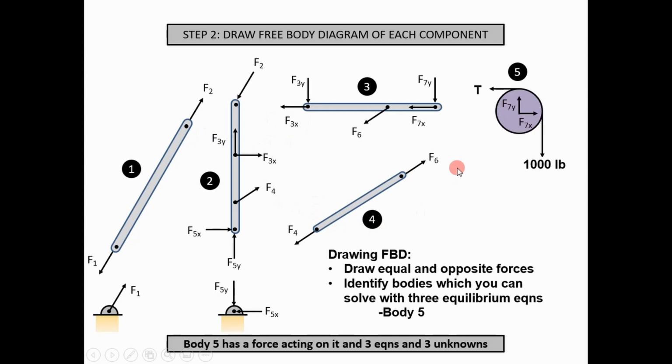And so the goal here is to basically take a step back and say, okay, I need to identify a body where I can solve for reaction force, and then I can translate these reaction forces down the line and solve for the others. So what you really have is three equilibrium equations in your pocket: a moment balance, a force balance in the x direction, and a force balance in the y direction.